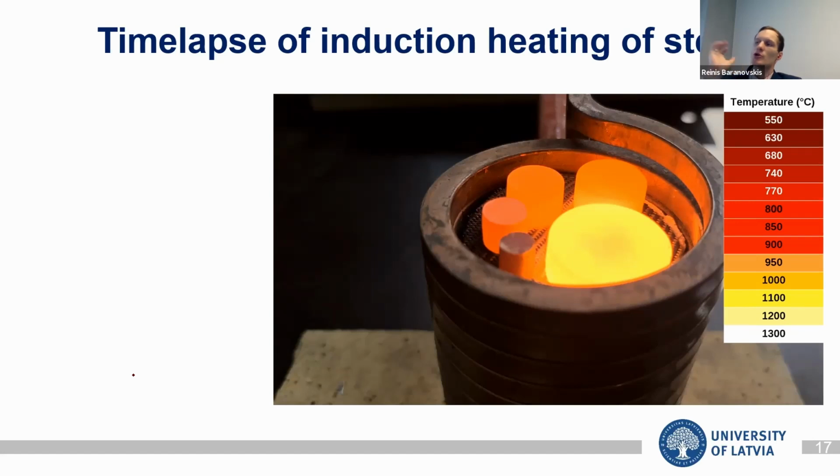That's used in induction hardening, for example, where you have a workpiece and you want to heat the outer layer of your workpiece. Let's say it's a crankshaft, and thus you can heat only the outer part of the crankshaft to change steel properties. It undergoes a phase change, and in the center, temperature has not changed.